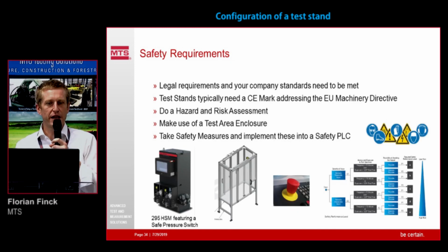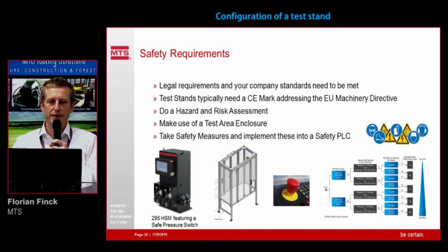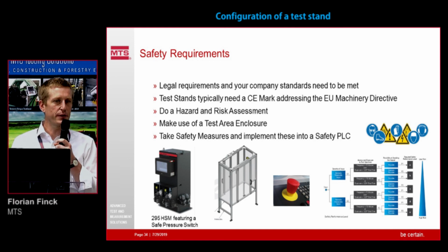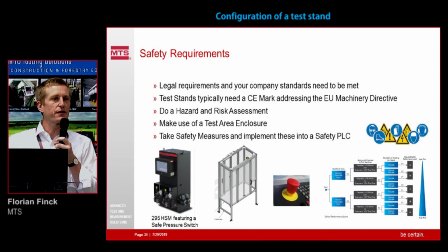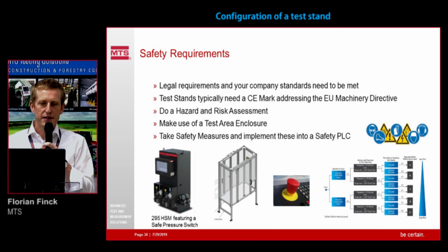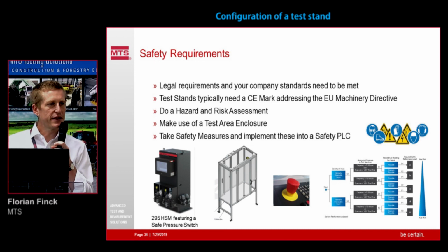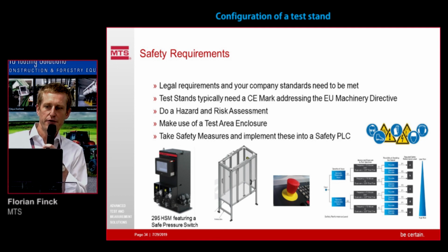And then safety requirements. So there's legal requirements. Your company will have standards that need to be met. A test stand, when it is a fixed application, typically needs a CE mark. So when you only have this, like looking back at that first example, actuators and brackets and things that are reconfigured once in a month, this does not need a CE mark. But the yellow machine, the second example, that is a very dedicated application that typically would need a CE mark